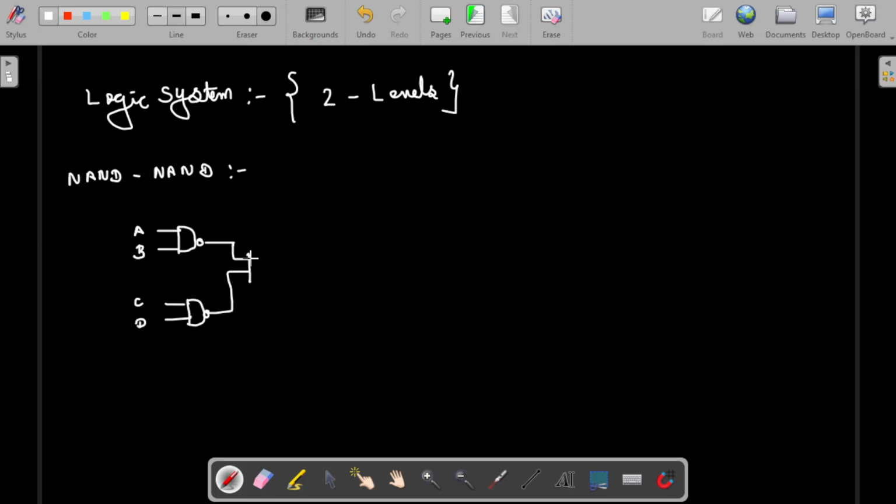And here we are going to give this to another 2 input logic gate. So this can also be equivalently written like this. Let's push this bubble to the outer side. Instead of making the whole bar, we can push this bubble here, so the result will come, right? Let me make it simpler.